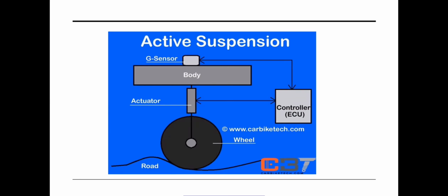The sensors are the eyes of the system, acting as a feedback element. These measure the process variables, which include wheel and body acceleration, suspension travel, steering angle, brake pressure, and throttle position. The ECU, also known as the controller, is the brain that receives all the sensor data. It compares the actual motion to the desired motion of the driver's needs. It calculates the error signal and then executes an algorithm to determine the precise damping force needed.